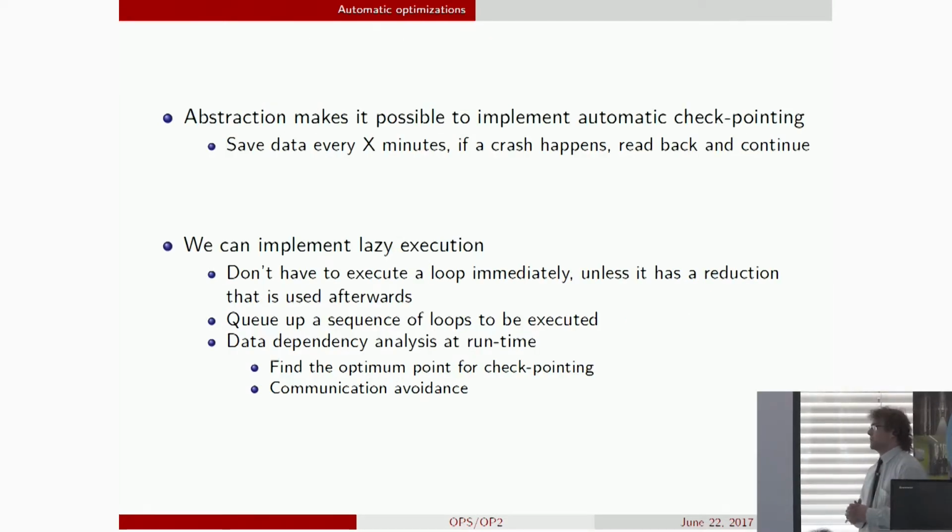And also the abstraction makes it possible to have automatic checkpointing. That basically means we save the data every X minutes, and if some crash happens, we just read back the data and don't have to start the whole simulation from the beginning, just continue from the last good results.